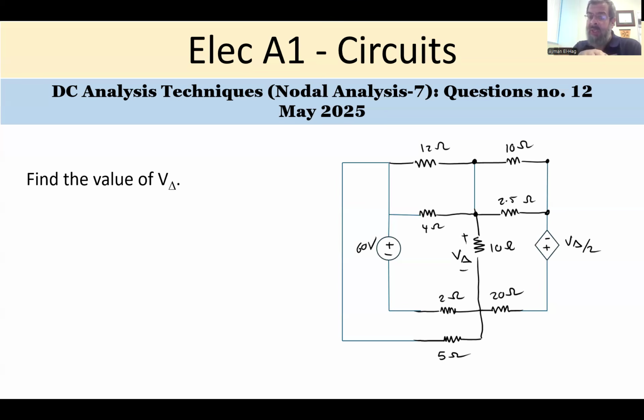So this type of question is DC analysis. Basically, the key point is that you need to do as much circuit reduction as you can, and then you can pick any technique. So you try to reduce the circuit until it reaches a certain level, and then you can apply nodal, mesh, or KCL, KVL. Personally, I like nodal analysis. I find it very efficient, but it's up to you. But here, the key point: never ever deal with the circuit in its raw condition. So let's see the question.